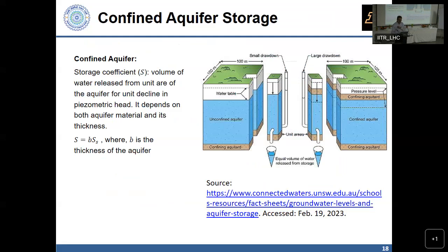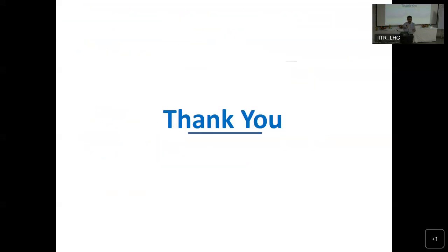Or in this case, if you want the same volumes, the amount of drawdown that you are going to get in an unconfined aquifer is going to be smaller than what it is in a confined aquifer. A lot more energy has to be expended to remove the same amount of water. Okay, I'll stop over here and see if you have any questions.